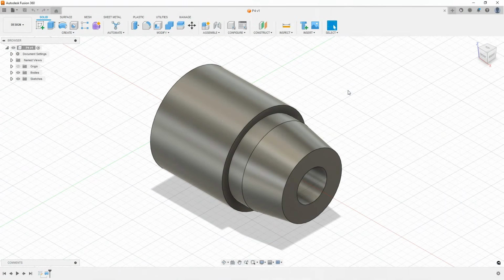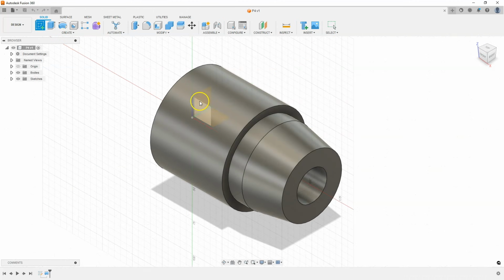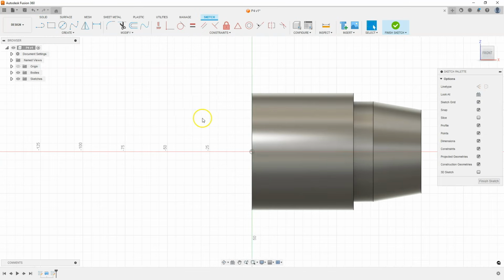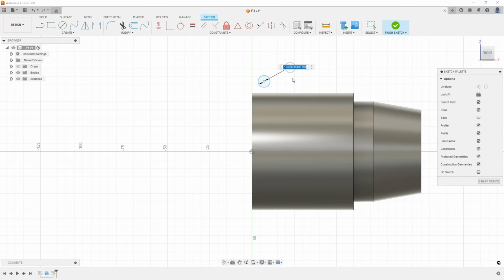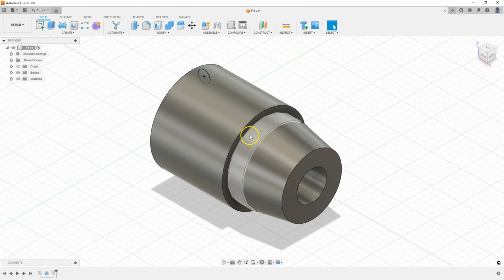When it comes to creating solids by rotating a sketch, we can also add a material cut by rotating the sketch. We will do it on the project created in the previous lesson. Create a new sketch, select the XZ plane as the sketch plane and create a circle. Okay, and select sketch dimension, select the circle and enter here 10 millimeters, and select this point and here enter 10 millimeters, and select constrain horizontal vertical and select this point, and click Finish Sketch to exit the sketch.